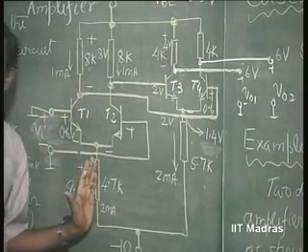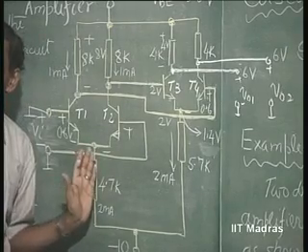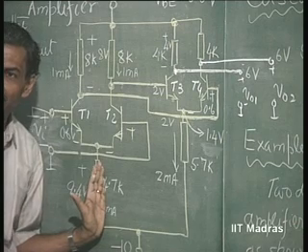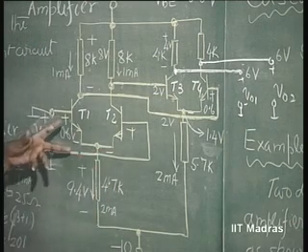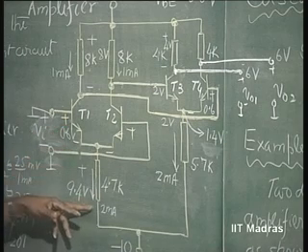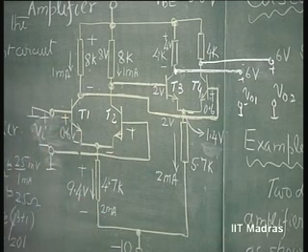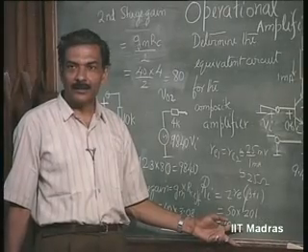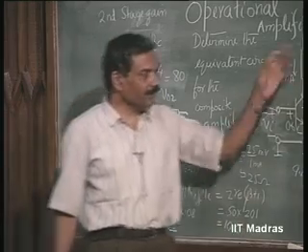So, the current has been excessively chosen here. The current could be made very small for the input stage. If I make the current very small, the input impedance will increase. If instead of 2 milliamperes I make it 0.2 milliamperes, the input impedance instead of being 10 k will become 100 k. Is this clear? And this will just work.